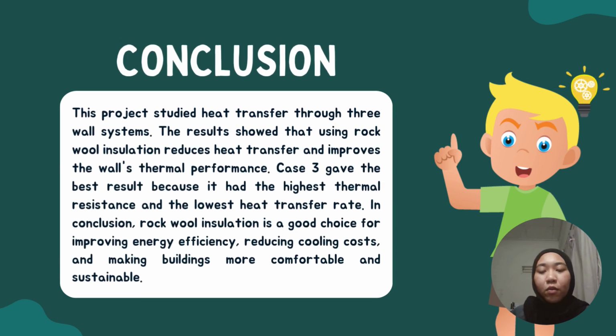So lastly is the conclusion. This project studied heat transfer through three wall systems. The results show that using rock wool insulation reduced heat transfer and improved the wall's thermal performance. Case 3 gave the best result because it had the highest thermal resistance and the lowest heat transfer rate. In conclusion, rock wool insulation is a good choice for improving energy efficiency, reducing cooling costs, and making buildings more comfortable and sustainable.